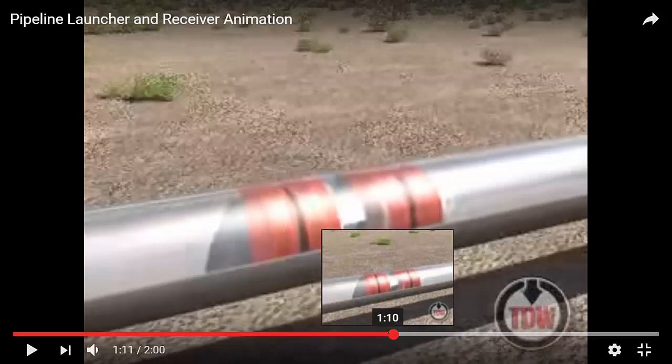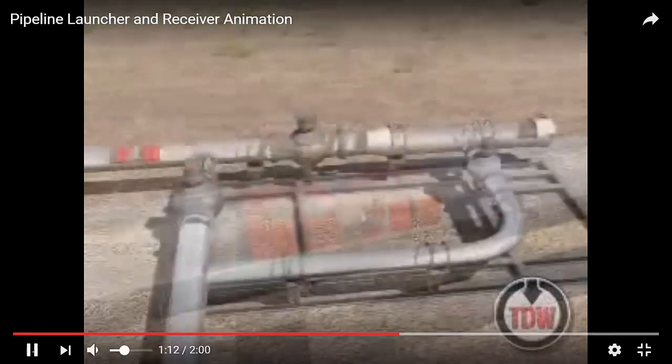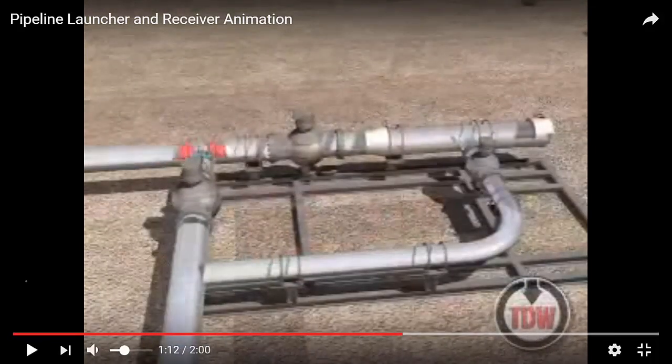I'm having the power fluid on the back, and all the scrap, all the wax, all my production fluids are in the front. The receiver is exactly the same system. Initially I'm flushing the fluid in this direction through this loop. Once the pig is inside, I'm going to close this valve and open this valve, and then bypass the pigging receiver. That's what I call a pigging receiver, and the other one was a pig launcher.